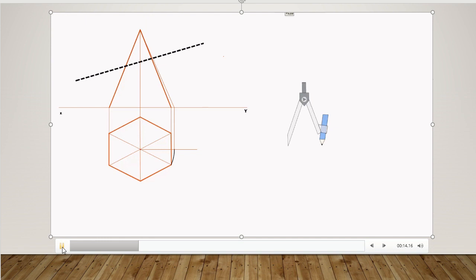After placing the sectional plane, transfer this point onto these two slant edges. Just watch it. With the vertical line, I am transferring the points to these two slant edges. Next, you have to transfer this point. In order to transfer this point, make sure you drop a horizontal line to the thin slant edge, after which project that point to this horizontal line. Then measure this radius and cut two arcs on this slant edge and this slant edge. Watch it.